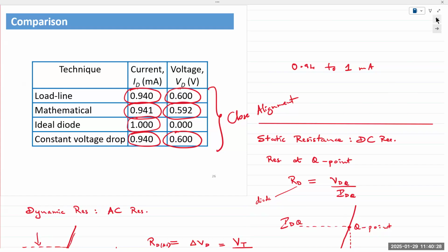We can model that conductor as having some resistance. In that same manner, any device that we have, whether it's a diode, a transistor, an FET, any kind of electronic device, will oppose the flow of current, and that opposition can be modeled as resistance. And that's the series resistor RS of the diode. Typically, it's very small. In the PSpice simulation for the lab, it was like 1 ohm. So it's going to be very, very small, but that's where it comes from. Does that answer your question? Okay.